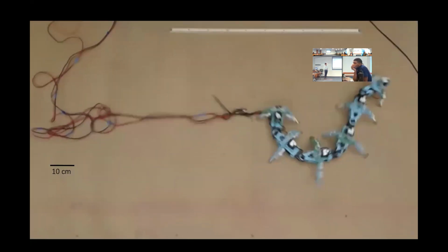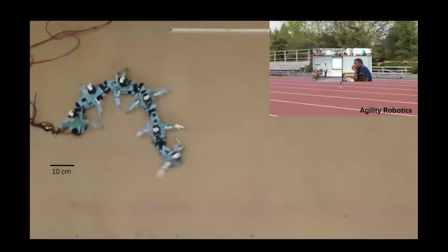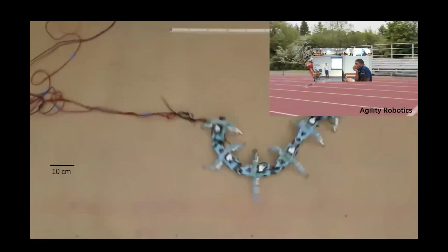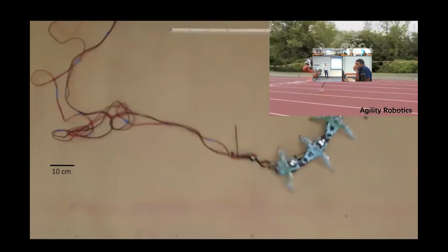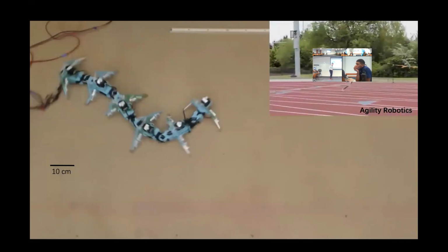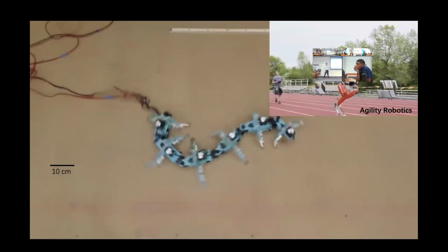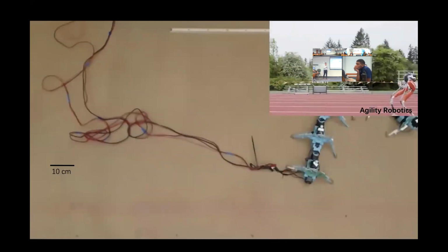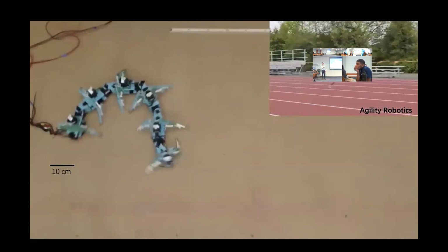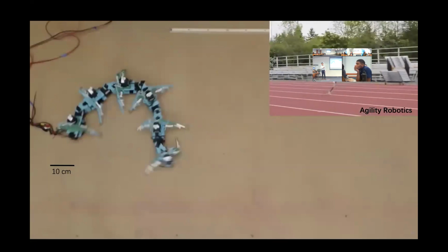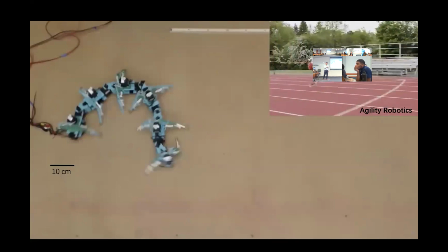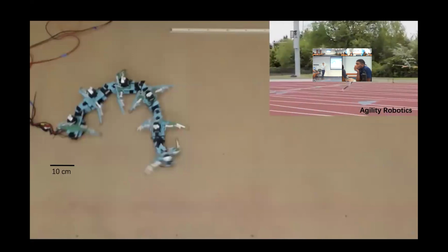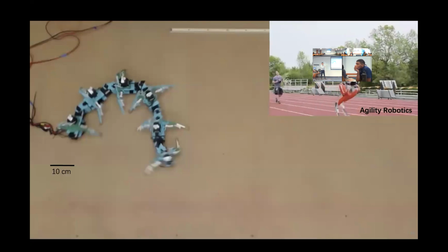And if we compare this 12-leg robot swimming to bipedal movement, we immediately notice that the thrust generation mechanisms are different. For bipedal, it's primarily legs. The legs contract and interact with the ground to generate forces. And for this 12-leg terrestrial swimmer, it seems to be the body undulations. If we circle back to our original question, how can we improve speed from the many legs? We have one hypothesis: it is the body undulation that does the job.